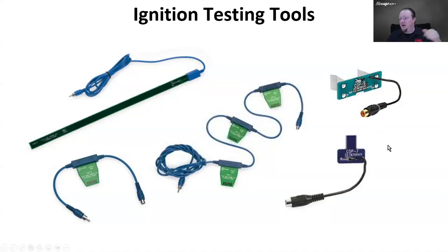And then there's also various part numbers of more vehicle-specific coil on plug adapters. There's one for like HEI. There used to be one for Ford. I think that one got discontinued though. Just clip over the side of those round coil that they had. There is one that's a COP11 that's kind of universal, and that one's useful, especially on the more modern coil designs we're going to look at in a little bit, where you can actually pick up a good pattern where others can't. We actually just redesigned it too, so that will be around for the foreseeable future as far as I've been told. The other ones are kind of specific to maybe older cars.